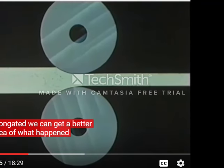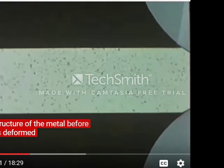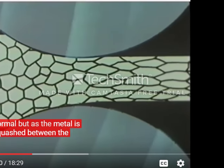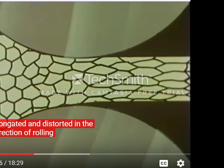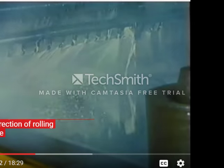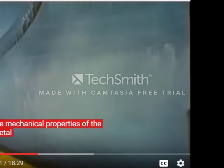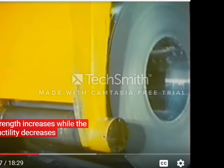We can get a better idea of what's happened in a diagram. First, we'll look at the grain structure of the metal before it's deformed. Here, the grains are normal. But as the metal is squashed between the rollers, you can see how the grains become elongated and distorted in the direction of rolling. The change in grain structure that results from cold working is accompanied by a change in the mechanical properties of the metal. Its hardness and tensile strength increases, while the ductility decreases.